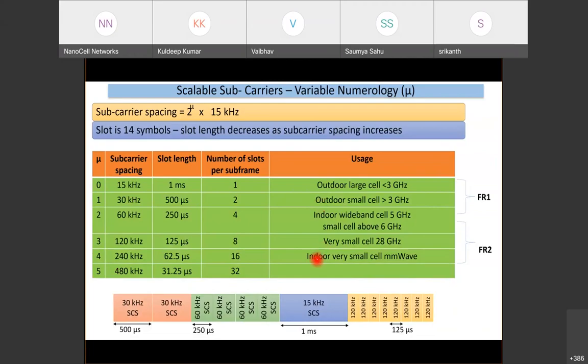As I mentioned, in some of the low frequencies, you will see 15 and 30 kilohertz being used. Okay. Some of these high frequencies, or rather higher subcarrier spacings, are typically tailored for some of the FR2 deployments. And even there you see some targeted towards indoor, small cell, macro cell. So these are some of the, you can say, deployment related nuances that can come into play when you want to choose the appropriate subcarrier spacing and the consequent slot length. Remember, slots are not fixed in time. Here you can see that in one more visual form.